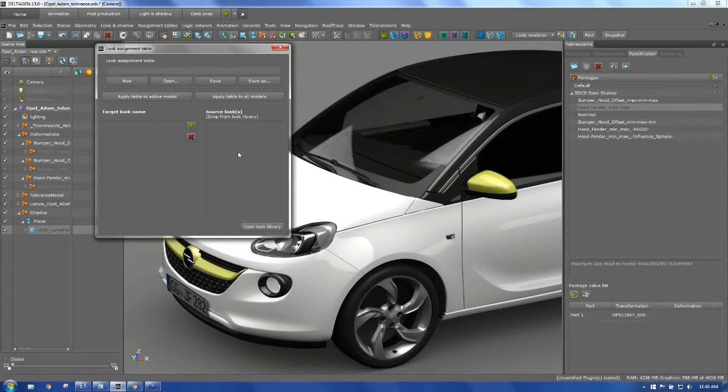If we associate a DeltaGen material to that, now every time I import something that says white paint, it will automatically assign a DeltaGen material that says white paint. So as you bring in multiple renditions of a spec study, you're not having to repaint them every time. It's a little bit of time to set up, but for your workflow from then on, it's a huge time saver.